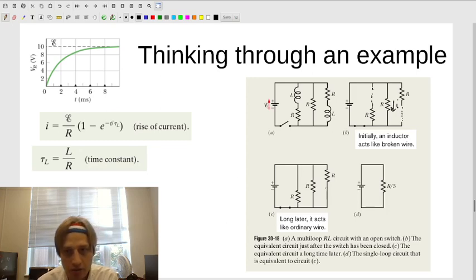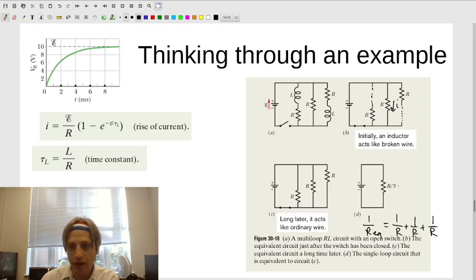They are sitting here storing some magnetic energy eventually, but the resistance of each one of these resistors is still going to add together like 3 resistors in parallel. And if you wanted to look at the equivalent resistance of this circuit, it ultimately would be the same as doing the 1 over R equivalent is 1 over R plus 1 over R plus 1 over R. And you'd still get that same equivalent resistance you would get for three resistors in parallel.